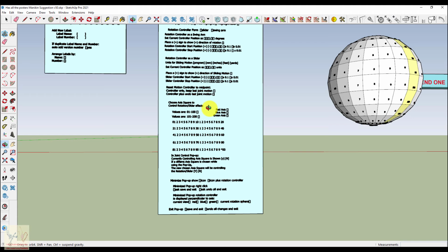And that's how human beings do that. And so it's my finding, it's my intuition, most of the time with moving mechanical structures, everything is going to be constrained except for one axis, or with respect to the sliding type of connection, one axis of translation or one axis of rotation.